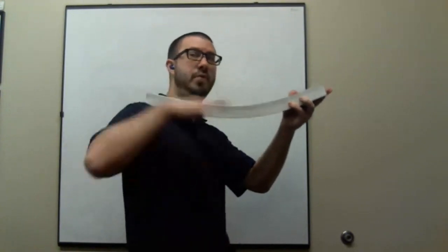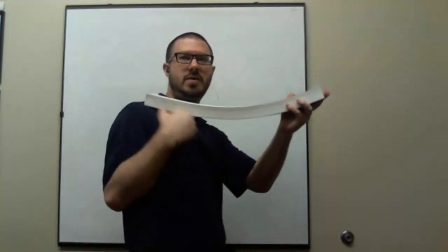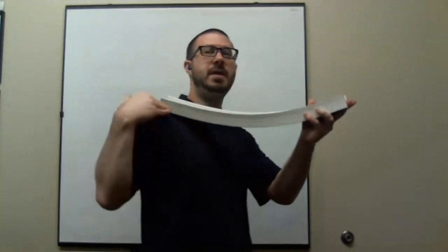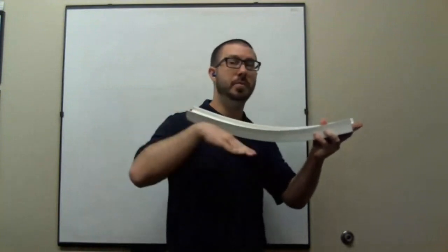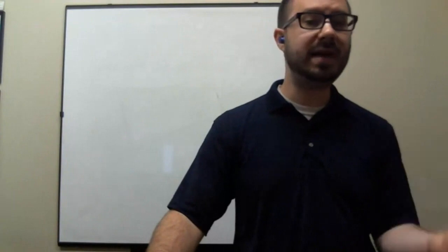Not only did it move up and down, but it also rotated. It has a slope to it. So if I take this point right here, this point is at a slope, and I might be interested in also determining the slope or the rotation of the beam. If I'm interested in determining the displacement, I apply a unit load. If I'm interested in finding the rotation, I apply a unit moment.